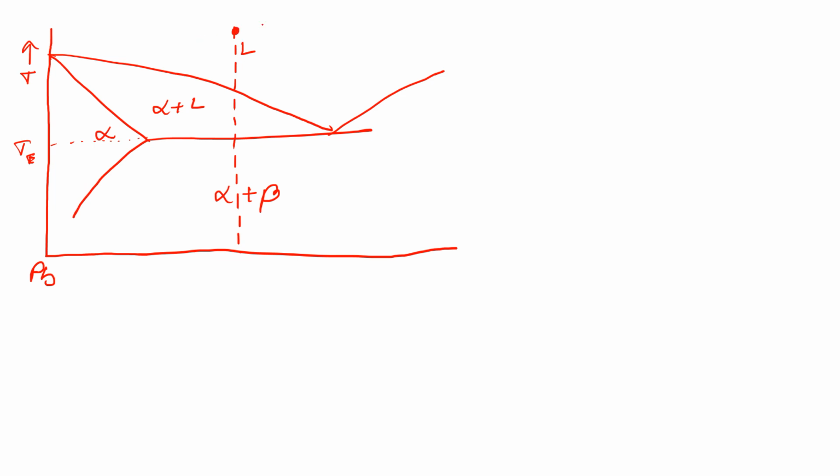We take a temperature which is higher than the liquidus temperature here for this composition, and then we gradually go on, here B, let's say C, just above the eutectic we have taken C, and just below the eutectic we have taken B. Okay, and this is the eutectic composition CE, and this is the C maximum of alpha that can be accommodated at eutectic temperature.